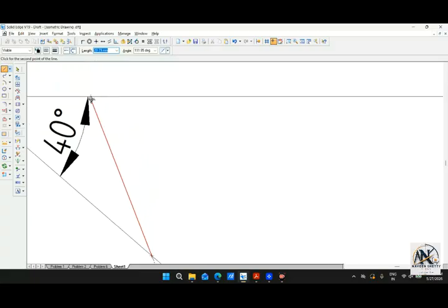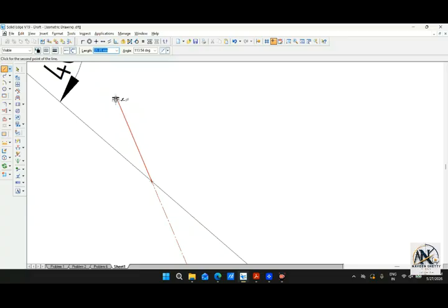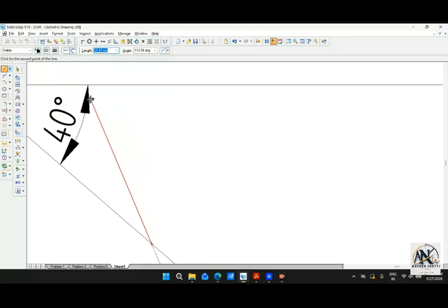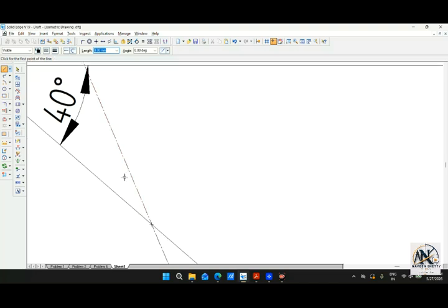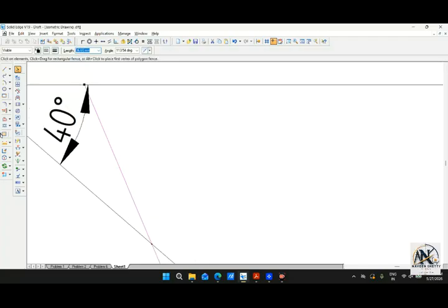And now use this. See, whenever it's going, it shows red. Or else, if you feel it is difficult, as I have told, use extend to next. When you take extend to next, you can see you get it. This line should always be a thin line, but I've taken it and it is coming as the center line. So this is finished.